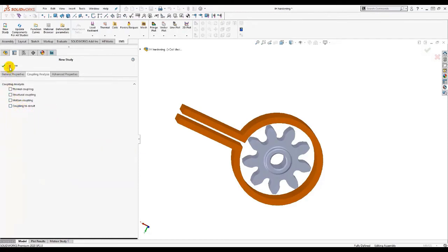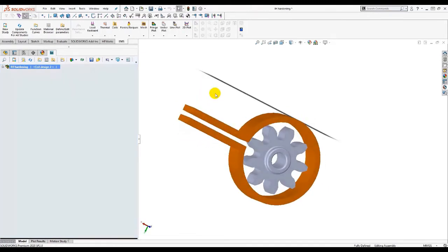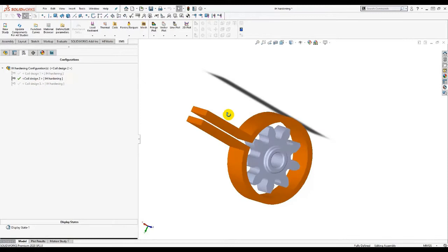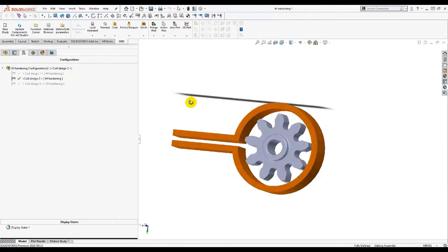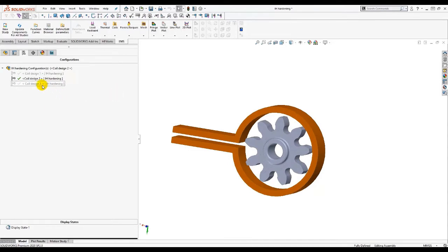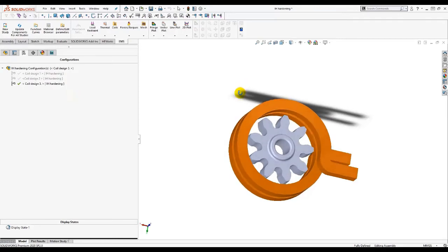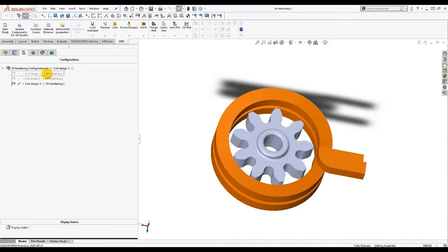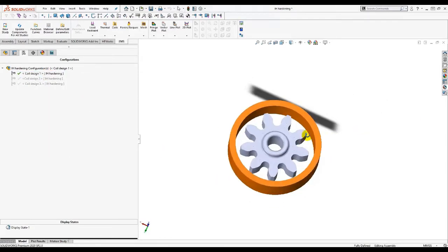Now, since we will work on the coil design selection, we already talked about SOLIDWORKS multi-configuration, which is available from this tab. This feature will allow us to study many coil designs inside the same project. As you can see here, with a simple click we can switch from one configuration to another, and the corresponding electromagnetic study will be activated synchronously. And here the third coil design.